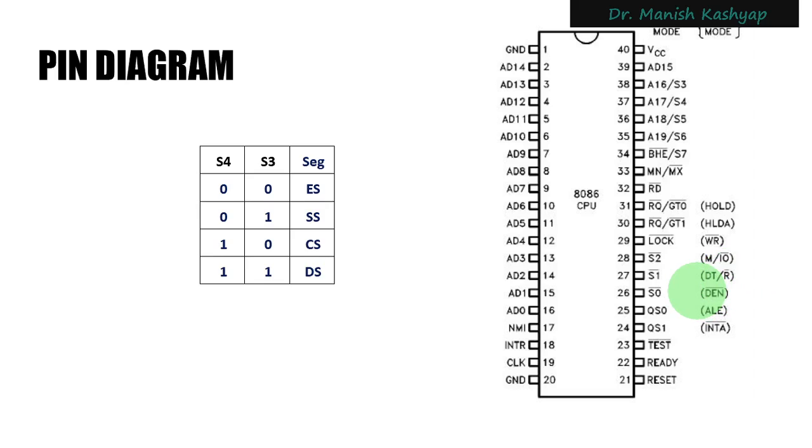So during every instruction that you process in this 8086 CPU, at the later portion of the bus cycle, this thing is done. In the minimum mode of operation, this signal is issued by the processor to enable the Intel 8286 or Intel 8287 bus transceiver.